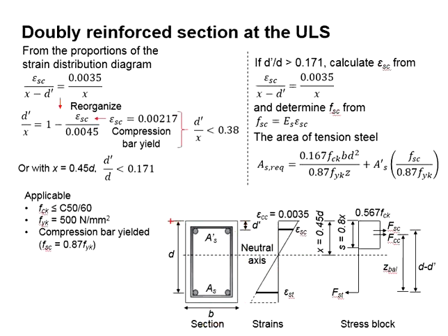Your effective depth will be calculated from the top surface of the beam until the centroid of your tension steel bar. To determine the effective depth, you will need the beam height minus the concrete cover minus the size of the shear link and minus half of the tension steel bar provided.